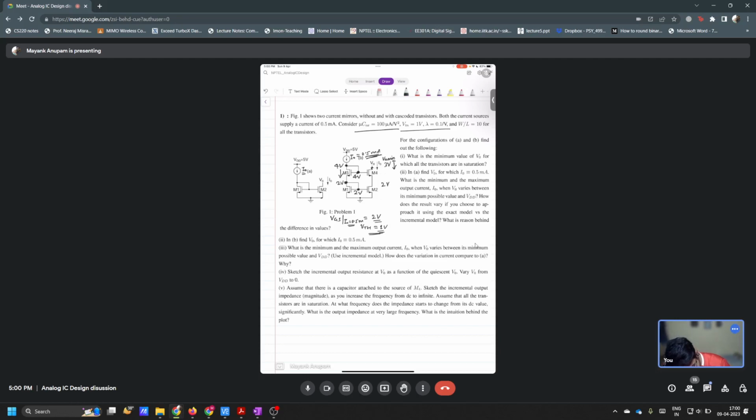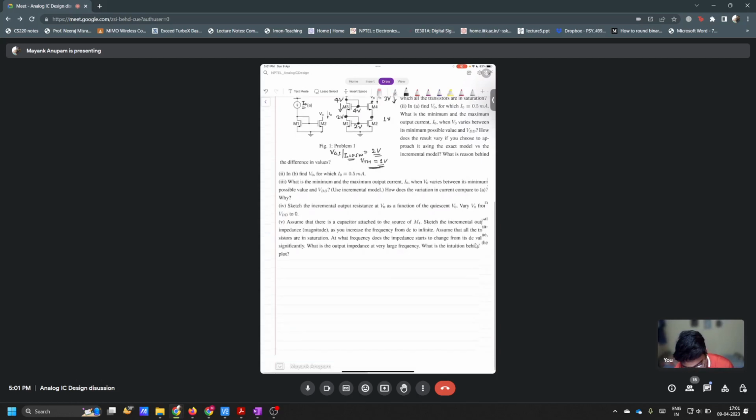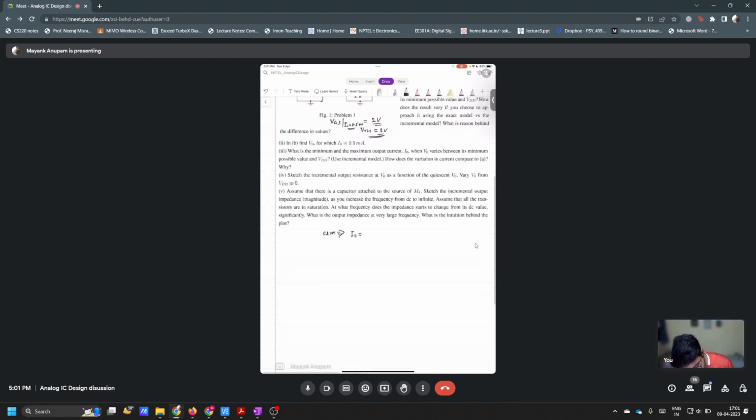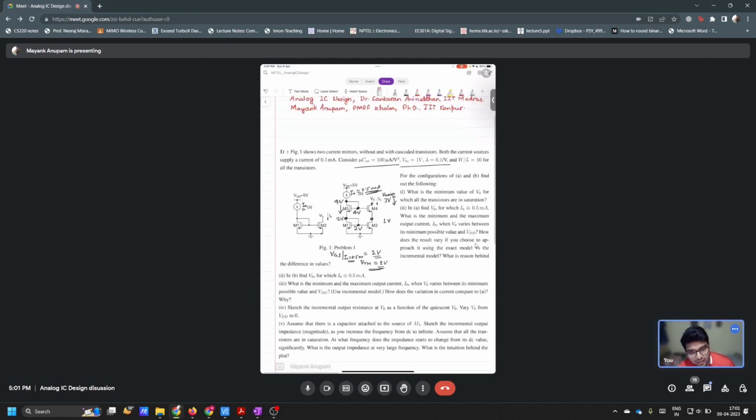Sir, in case of non dependent, so this is gamma into VGS, in small signal mode. Are you talking about body effect? No, how depending on VDS you are telling. I am not understanding what you are asking. You were telling that it's dependent on VDS also. That I'm not getting. So if you assume channel length modulation, what is the equation of current? I naught is equal to what? I naught times 1 plus lambda VDS. Okay, that is what I am saying. Is that clear?